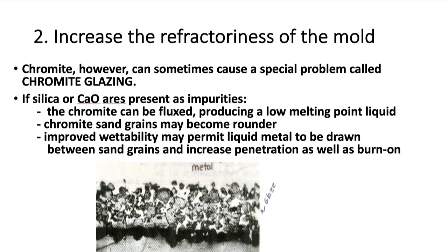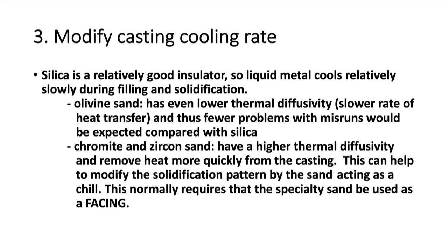And can you imagine when you grind this stuff, it has these really hard particles in the surface. So my abrasives, which are essentially oxides, are trying to remove oxides that are on the surface, and they do break down. By the way, we do use diamond more often. They're using diamond wheels and diamond grinders to start grinding this stuff, and we get much longer life.